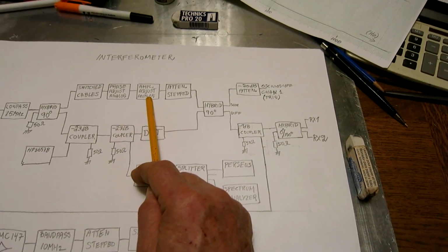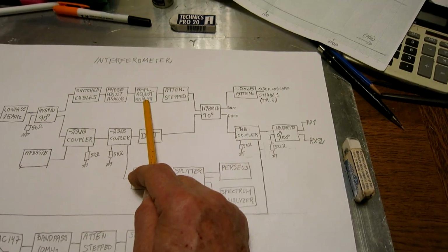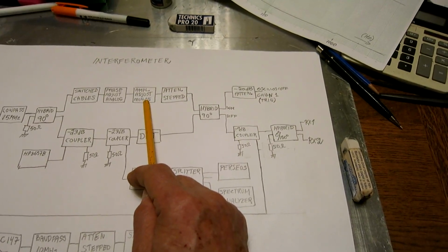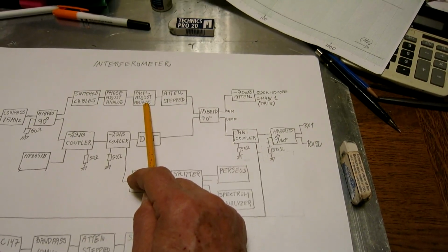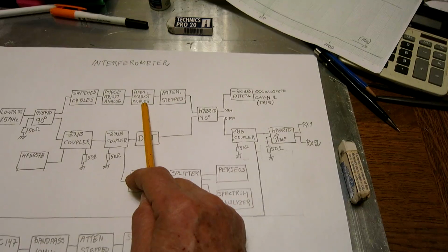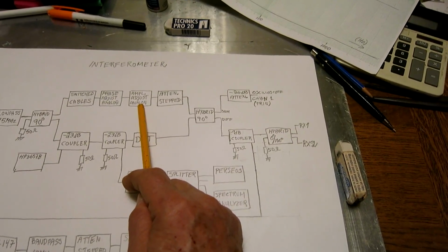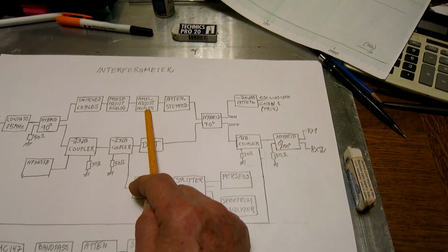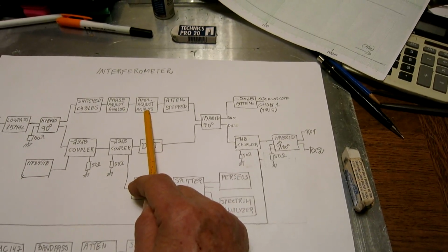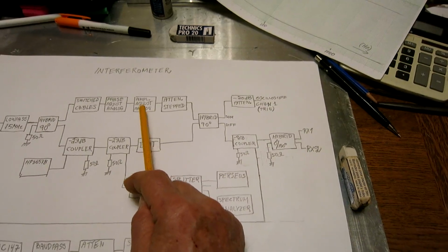And the capacitors have a maximum capacitance of the smallest 11 pF, the next one 40 pF, and the biggest one 150 pF. And the resistors are adjusted to make the tuning range suitable. The biggest one has an inductor in series to not produce any phase shift in its maximum attenuation position.